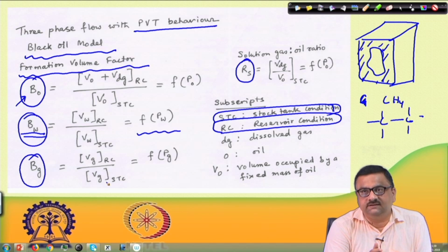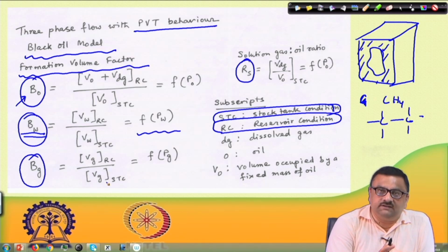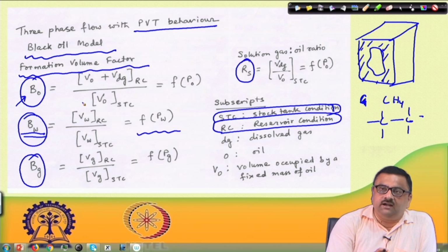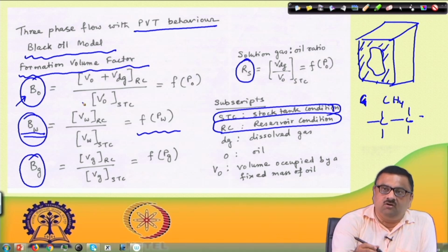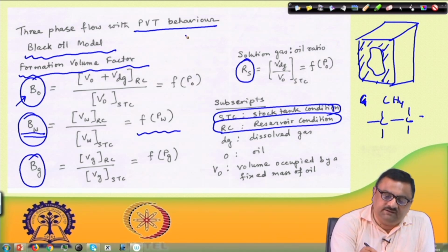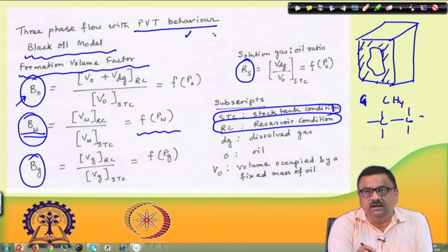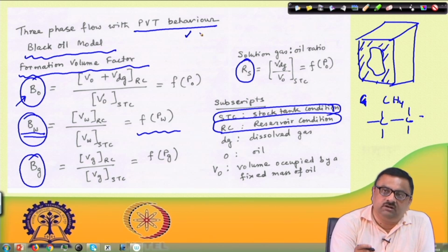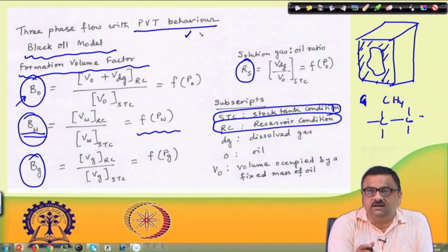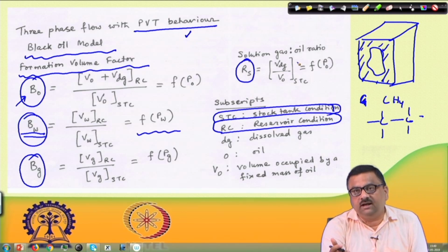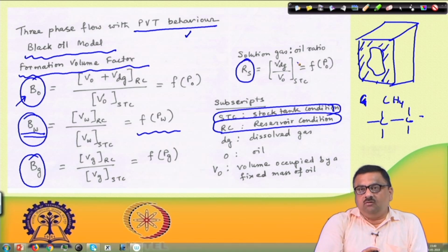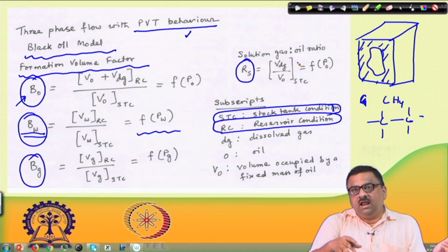We have studied already in physical chemistry how it is to be done, but instead of going to those correlations, the idea here is to work with these parameters and try to write the continuity equation, because we have to write a continuity equation for oil. Remember, originally there was a continuity equation, then we said that we can use KRO, KRW, relative permeability to oil, relative permeability to water, and use Darcy's law. But now, in the Buckley-Leverett form, the situation was much simpler. There we had only oil and water at interstitial saturation, and only water was injected.